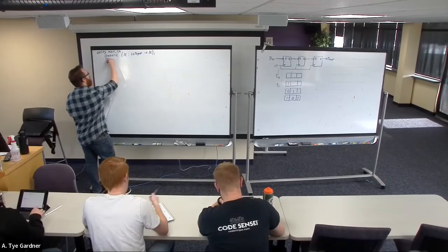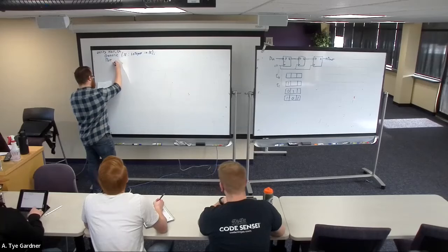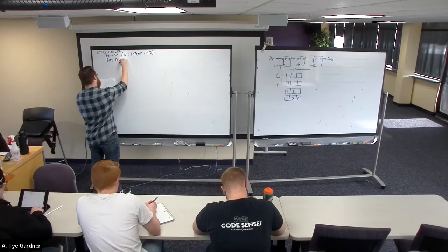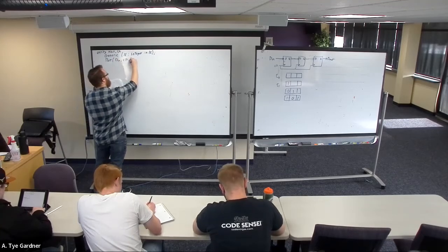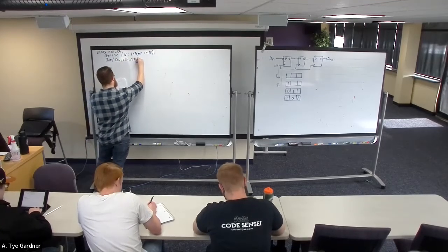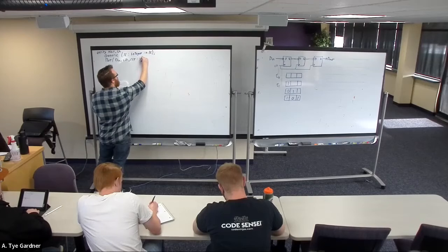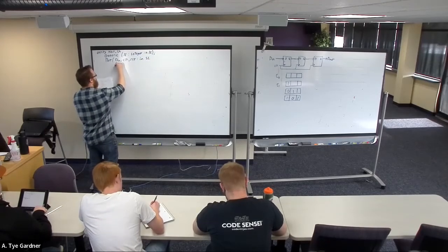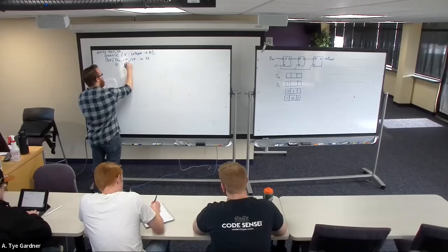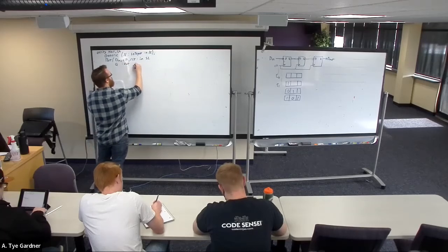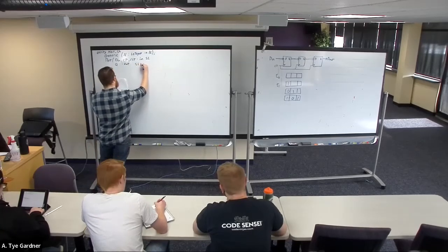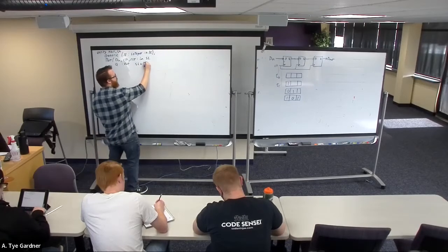Then I do the ports. And we're just going to call it essentially D, N, clock, reset. These are inputs of standard logic. And then we have Q as an output of standard logic vector. And here's what's fun.